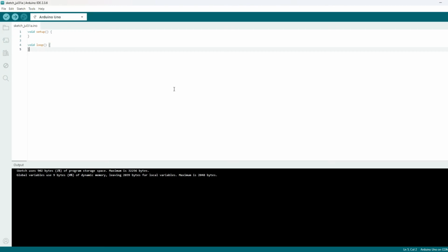So, to code an RGB LED, it's actually really simple. It's basically just like coding 3 separate LEDs, the red one, the green one, and the blue one, and make different combinations of them with the analogWrite command to make all our colors. So that means we're gonna have 3 pin modes. In my case, I chose the pins 3, 5, and 6. Output, of course, because they are LEDs. So I'll just do this 3 times. And 5 and 6. So that'll be all our pin modes.